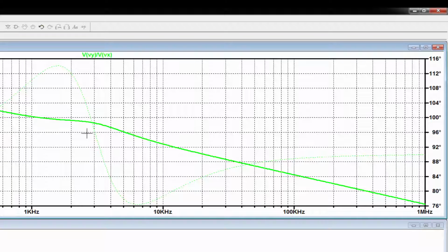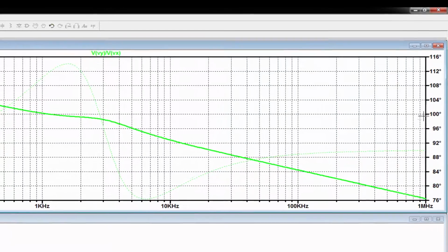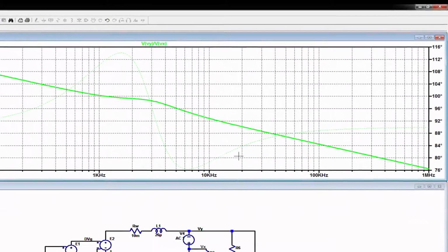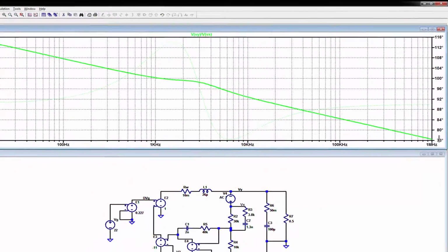Well, but you had a Q. If you get a Q, it moves the bandwidth out a little bit. See? And look at your phase margin, where it does cross over here. Your phase margin is right over here. You have to subtract the 90 degrees, and your phase margin is pretty high, because you can see we have the double poles, and the ESR is 0 coming in. And then your gain margin is where the phase crosses over at 0 degrees, but we never get there, so the gain margin is way out. It's greater than 30 dB right here.